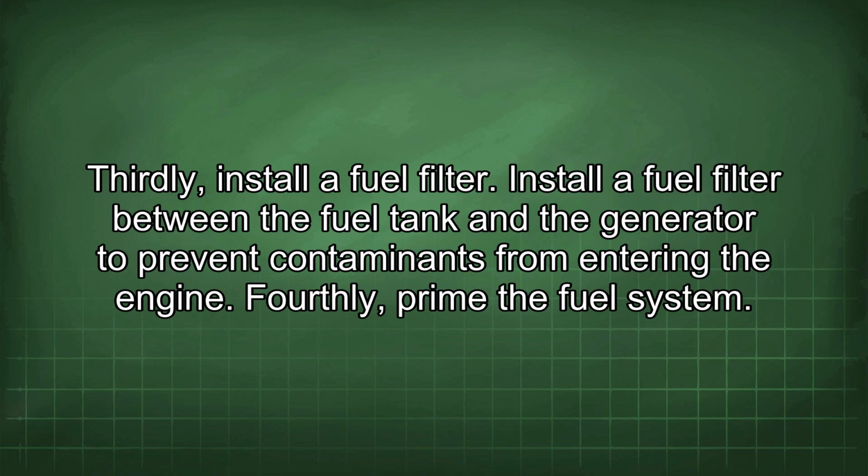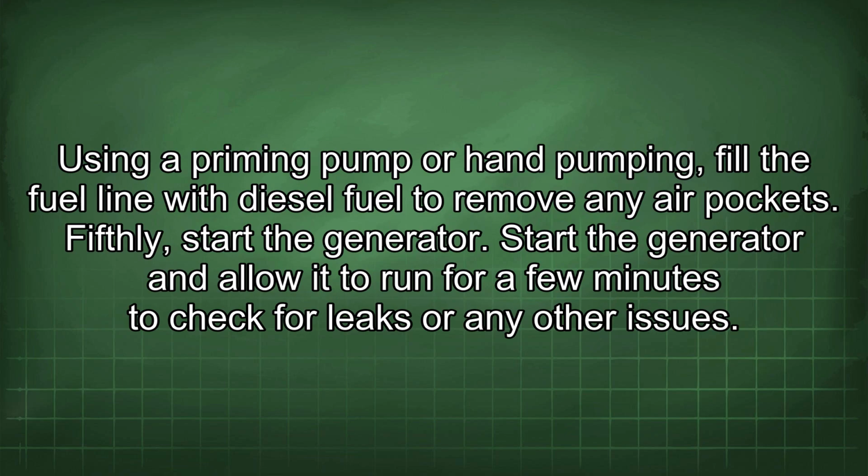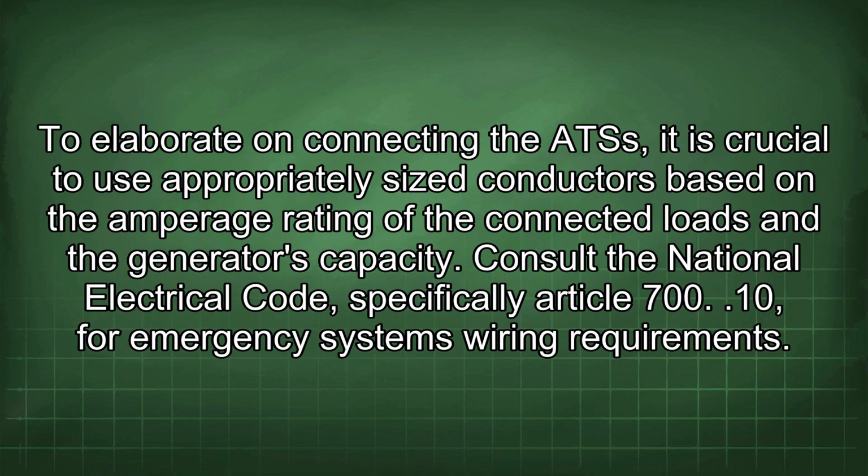Fourthly, prime the fuel system. Using a priming pump or hand pumping, fill the fuel line with diesel fuel to remove any air pockets. Fifthly, start the generator. Start the generator and allow it to run for a few minutes to check for leaks or any other issues. To elaborate on connecting the ATS, it is crucial to use appropriately sized conductors based on